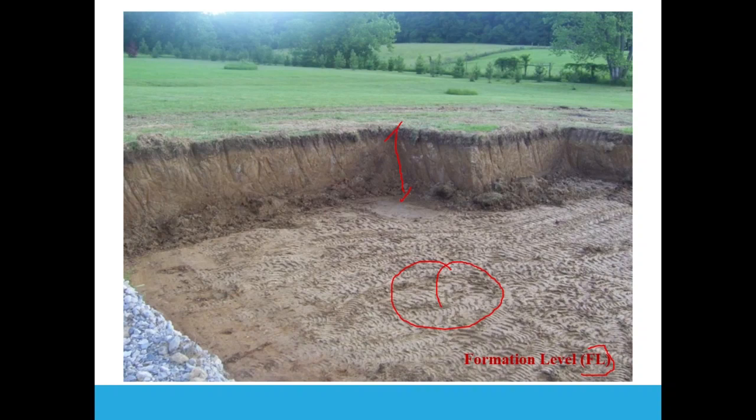So as you know, it's very easy to calculate the volume if this area is flat. The volume of the excavated soil would be the area here times the height or the depth of the excavation. So this is based on an assumption that the ground here is flat. So if it's flat, the volume would be the area times the height or the depth of the excavation, this one. So this is the volume.